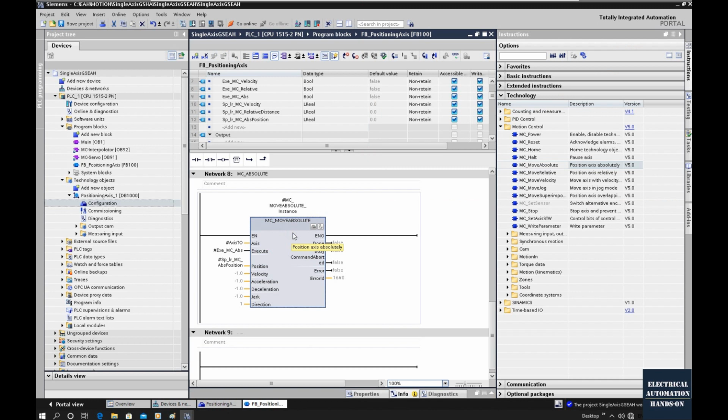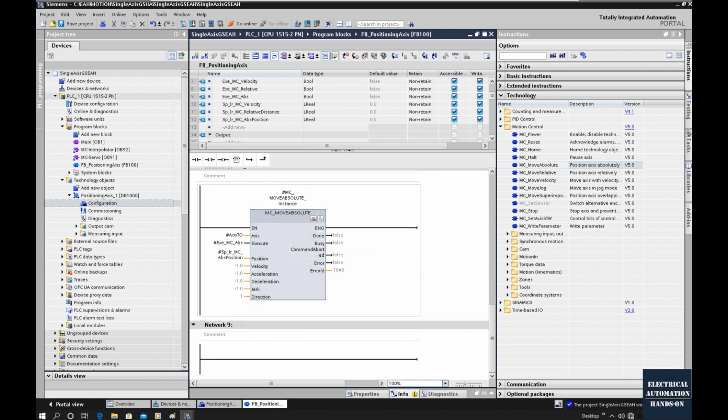So that means if you can organize the trigger, positioning command and signals very well, one function block here is enough. But if it's too complex for you, you can still use individual function blocks. Every positioning control can represent each individual position, so you can trigger them individually.